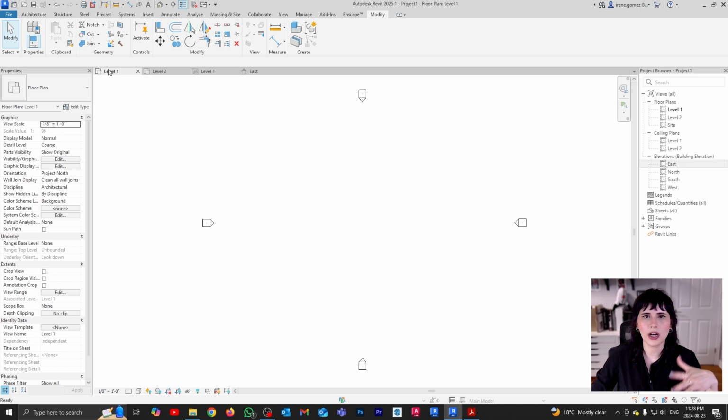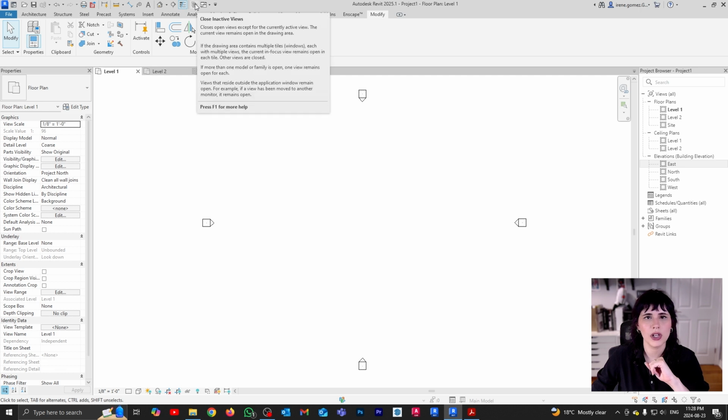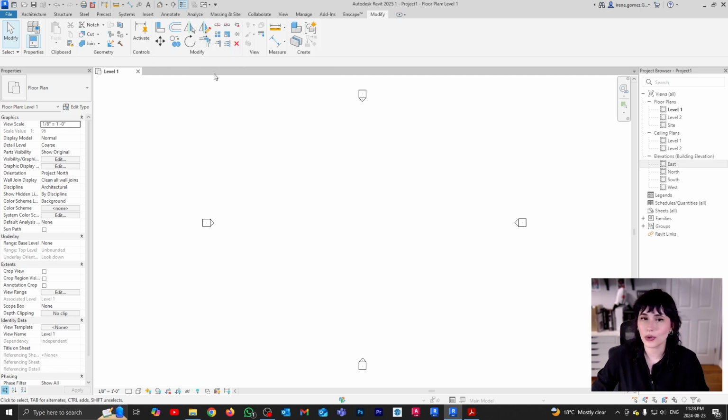Now, let's say that I'm done and I don't want to have all of these tabs here. Well, if I want to get rid of all of them except the current tab, instead of me having to go click, click, click, what you can do is come all the way here to the top to close inactive views and click. And that's going to get rid of all inactive views.